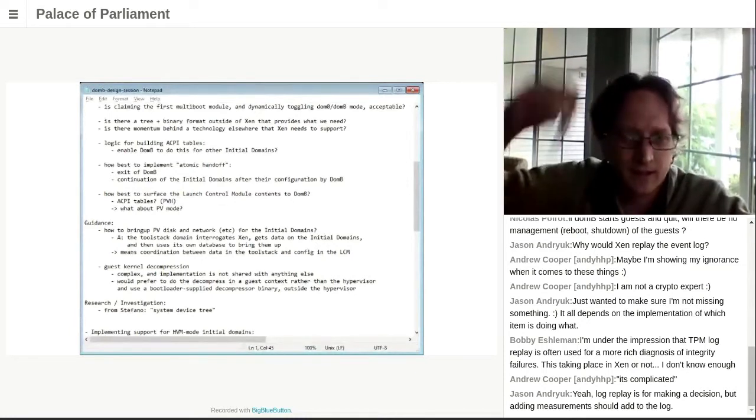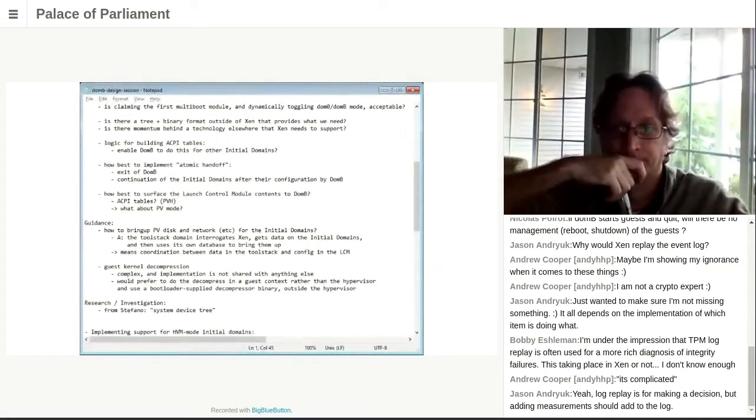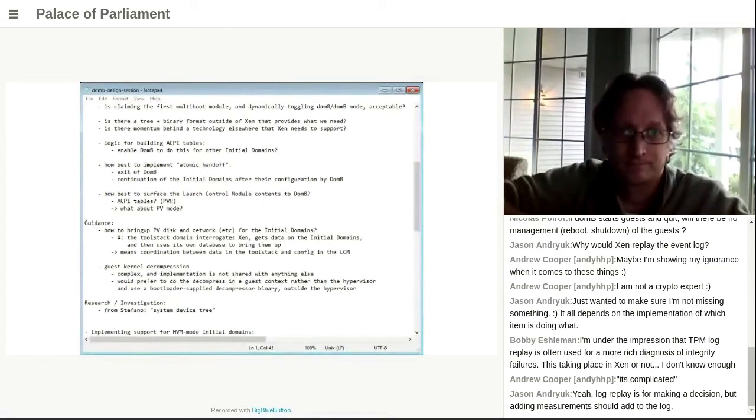Okay, and is that a pretty static piece of code? It's very static. Okay, and pretty widely deployed. Yes, it's used everywhere. So that's one thing they did right about device tree. It came with the reference implementation in libfdt, and then they wrote libfdt so that it could be used both on the build host as well as at runtime in the kernel. So libfdt is basically used everywhere, from DTC to U-Boot to Linux, Xen.